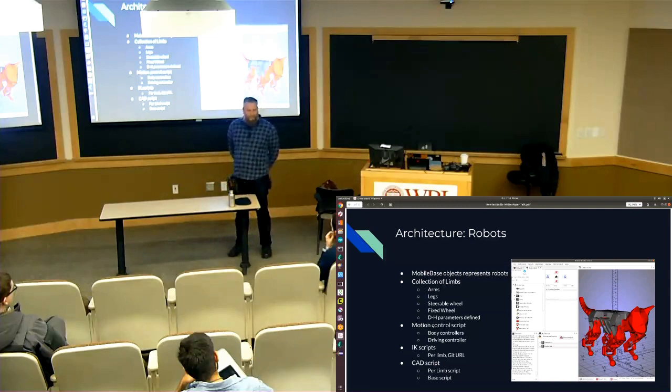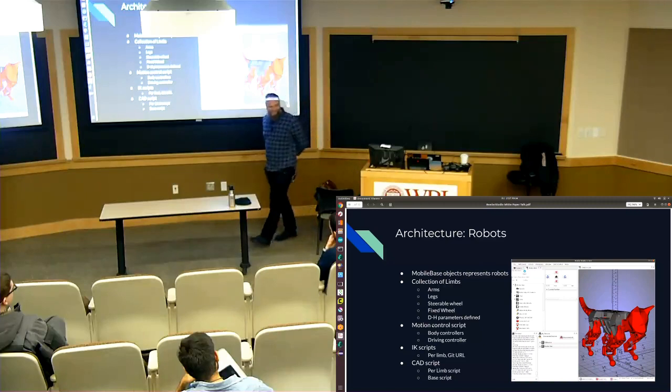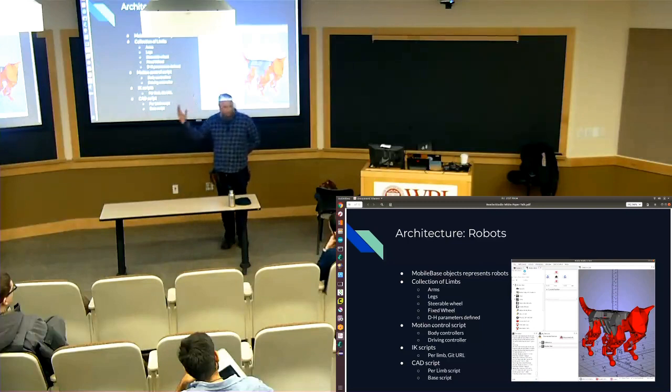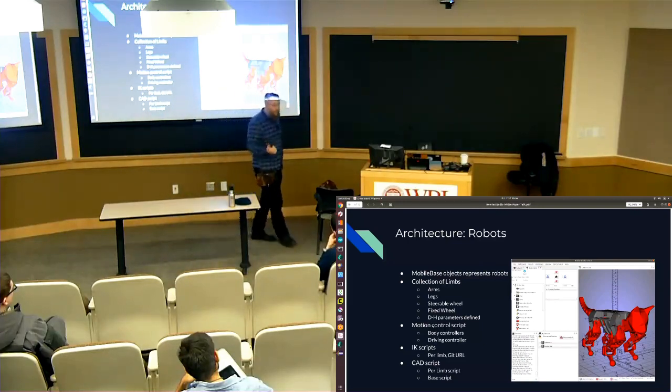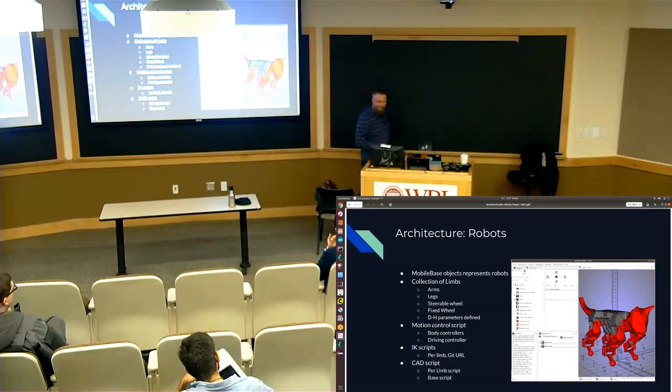Well, the idea being that you can define an arm that would be the same shape, but is it valid? Or is it in some way breaking a rule, which is otherwise known as modified DH parameters? The modified being the cheat, obviously. So yes, you can make modified ones in here. It won't break. It doesn't actually do that validation check, but strictly speaking, if you do it right once, there is only one. There are skews, cases where you may have arbitrary choices, like for instance, if two z-axes are intersecting, then you may take an x-axis going one way or the other way, so on, if it's planar.